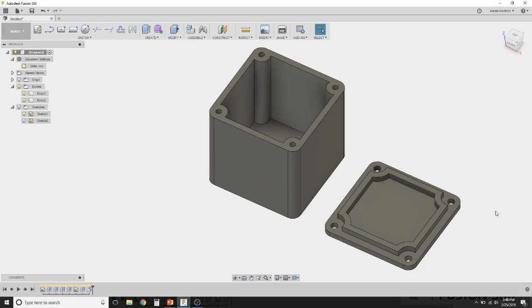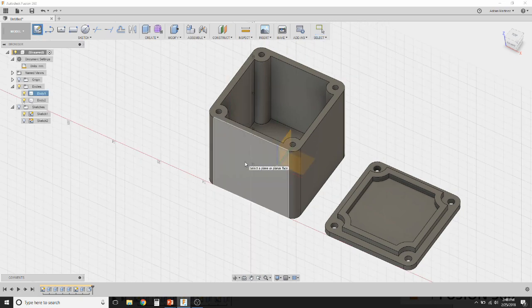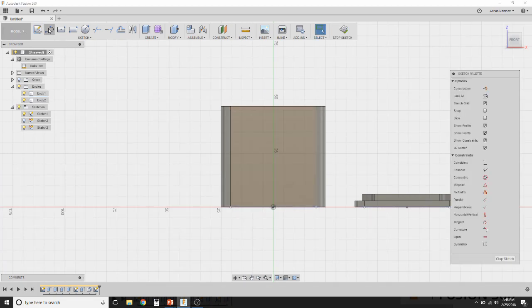Now you can use the ability to create sketches to do a lot of other things. For example, I can click create a sketch and select the face of the box. I can use a line to give me something on a center point. If you notice here, just like when you hover over the origin, you get the little square, when you hover over the center of a line, you'll get a little X and a triangle, and that indicates the midpoint. That's your midpoint snap indicator. You click and drag along until you get to your origin point, and now you've got something going from the midpoint that's perpendicular, and that's a straight line.